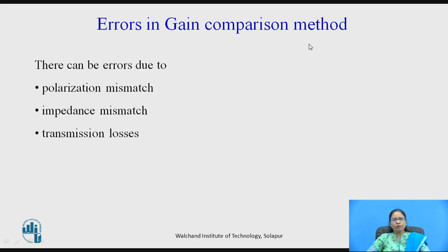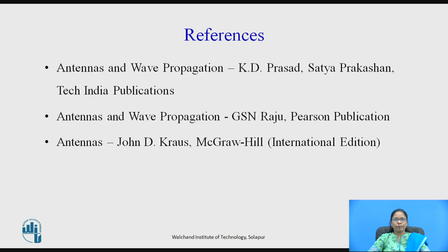There can be errors in the gain comparison method due to polarization mismatch, impedance mismatch, and transmission losses. So this is the video about gain measurement, and these are the references used for preparing this video.